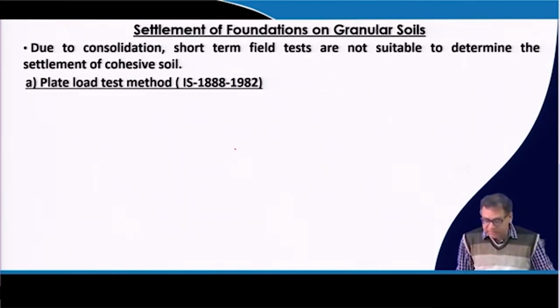The plate load test is done in the field. This is the field test for the shallow foundation, by which we will get not only the settlement but the bearing capacity of the foundation also. The advantage of this test is that with most field tests we determine the soil parameters directly or indirectly, then use those parameters in our bearing capacity equation to get the bearing capacity.